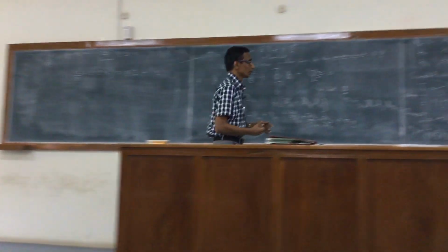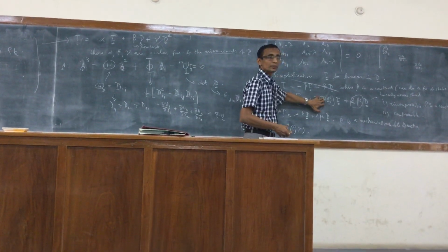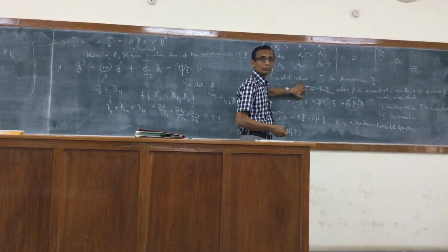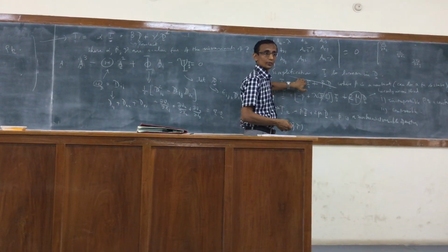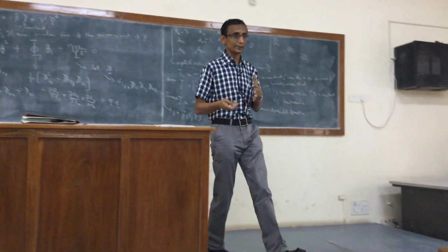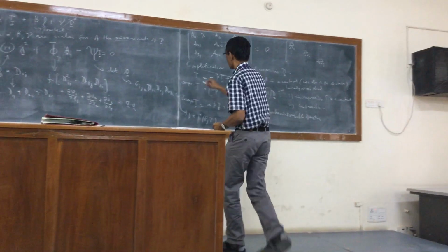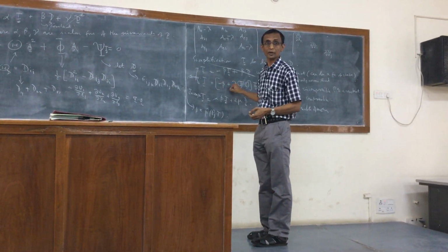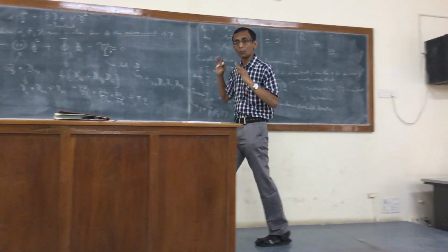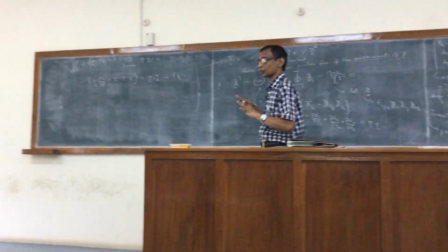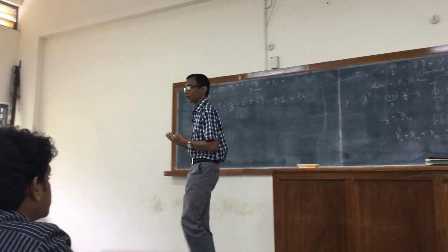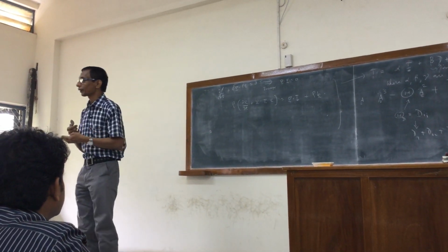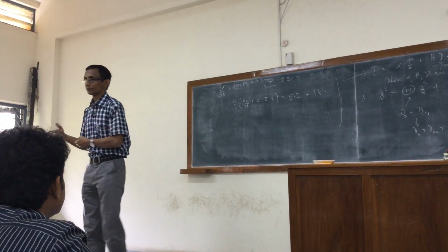Right? So this form, as well as this form, reduce to the state of hydrostatic stress when D is equal to 0. Clearly, compare these two. The more general form is this. So I have to allow for this. When we talk about the most general form consistent with Stokes' hypothesis, there is the additional restriction of a linear relation between T and D.